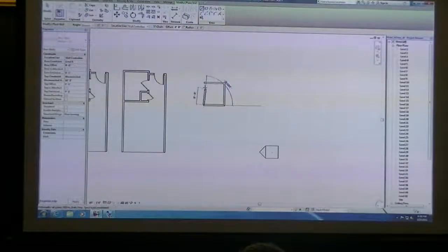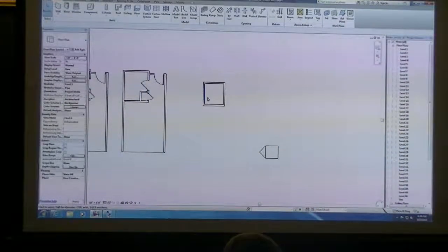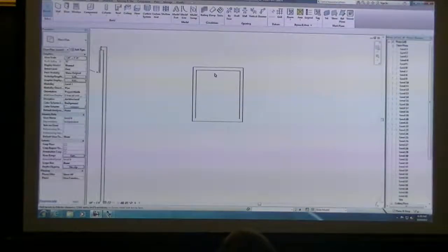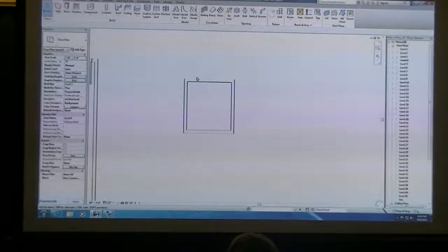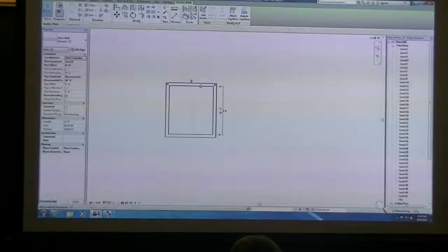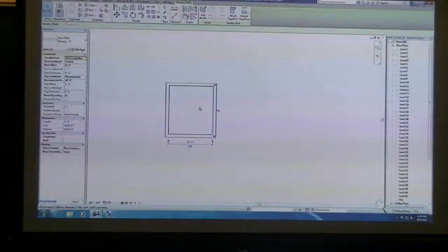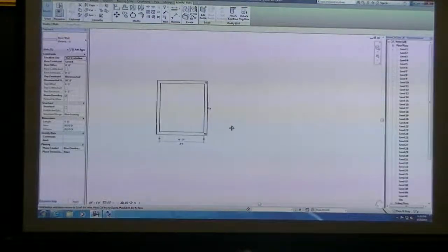Any questions that came up while you guys did the assignment in regards to walls and doors? Essentially what I want to talk about is when you're drawing with the walls, it's pretty self-explanatory. You're drawing lines, but it's making a wall for you. To manipulate dimensional data within any room or space that you've made, the way Revit works is you normally start placing your walls and drawing a little bit, and then later on you come back and change your dimensional information.